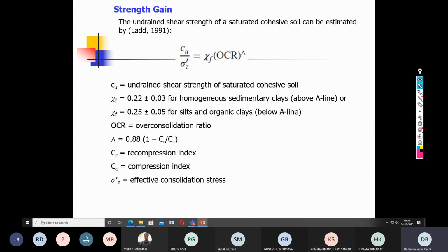were talking about the accelerated consolidation. Now, when I say consolidation, it is obvious that we are anticipating a huge amount of settlement, but is it only the settlement that is happening without improvement in the soil strength, or will there be improvement in the soil strength as well? So when you are inducing more and more settlement, there is a change in the over consolidation ratio. So accordingly, they try to correlate what should be the improvement in the cohesion value as and when the consolidation is progressive.